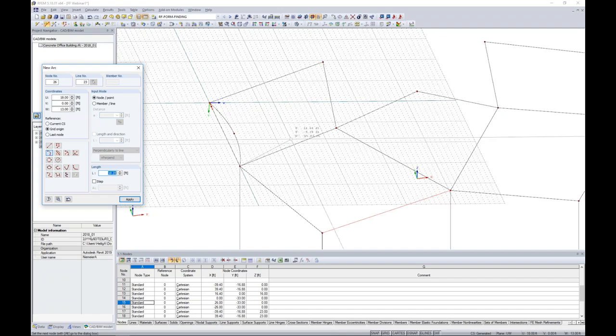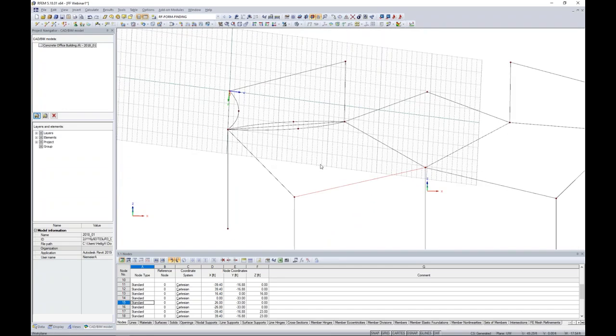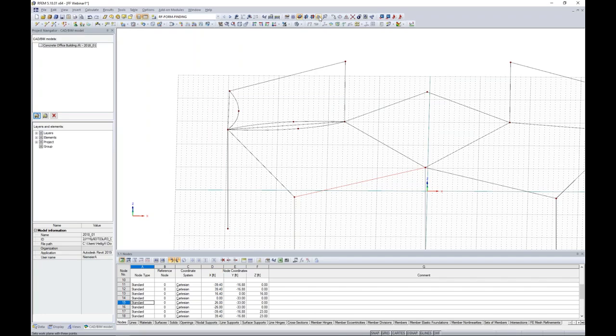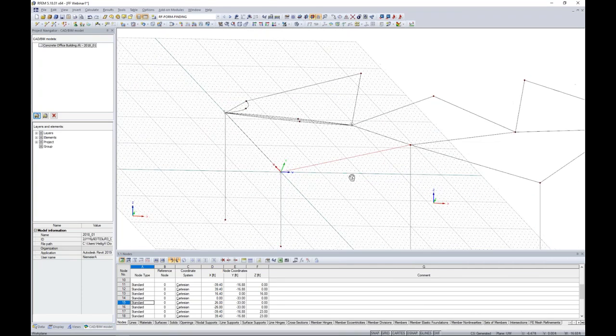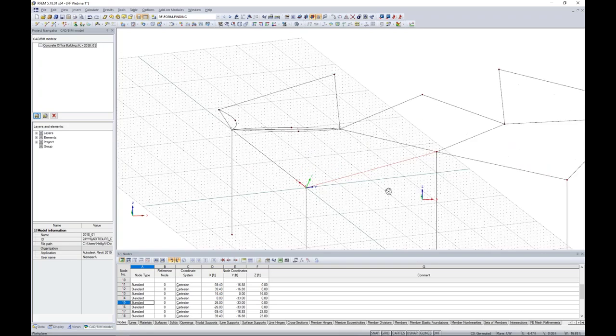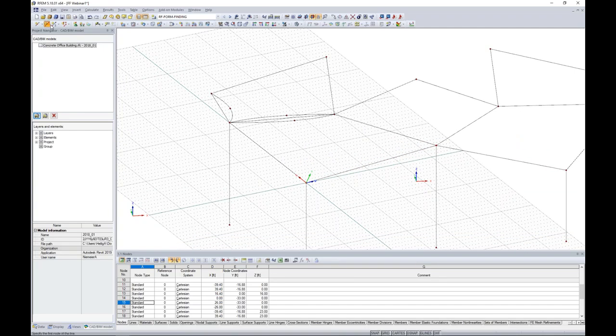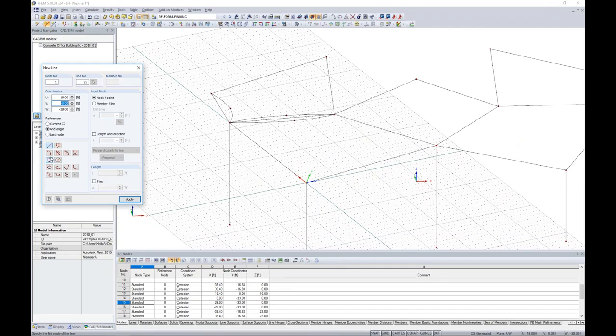I'm going to do the same thing at a different location here for my cell points. Again, completely arbitrary. We need to move up to the second cell, and we need to change our user-defined drawing grid. So I click first to reset the drawing grid, click it again to define my new point, and I can click on 3 points here. Now you'll notice that I have a new drawing grid at a specified angle. So we go to draw a new arc, and I can simply snap to these points, again, any arbitrary points.